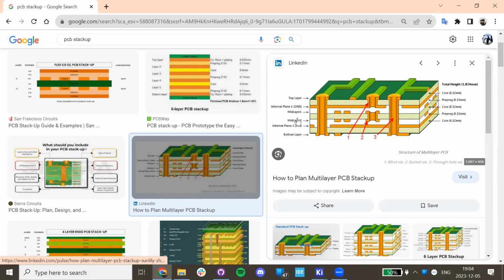And yeah, please stop me at any time if I'm saying something stupid. And then you have the layers, which are in copper here. Usually when we do PCBs, most are 2-layer, but we have some 4 and 6-layer boards as well. And the thickness of these layers can be chosen. Usually it's given in ounces or the thickness in actual millimeters, so ounces per square foot or something like that. Our PCBs are usually 1 ounce.